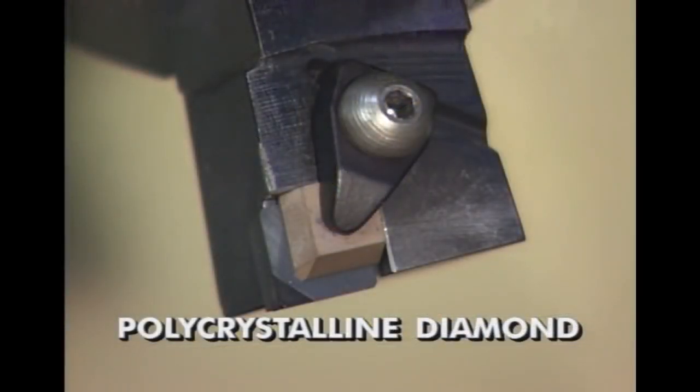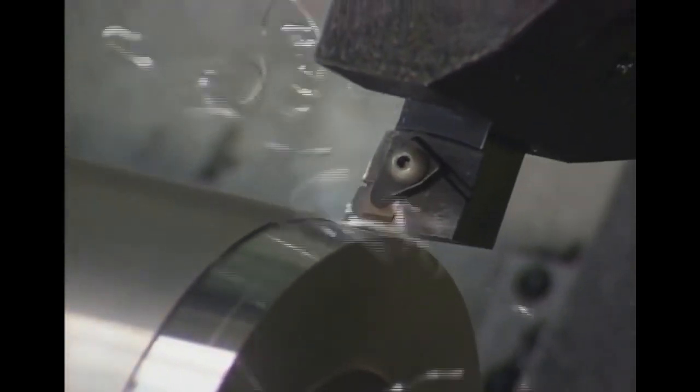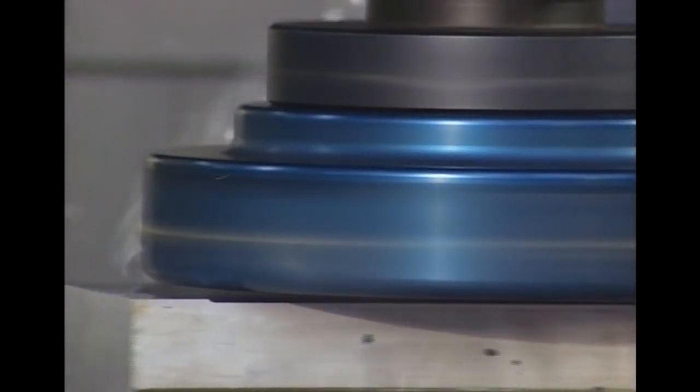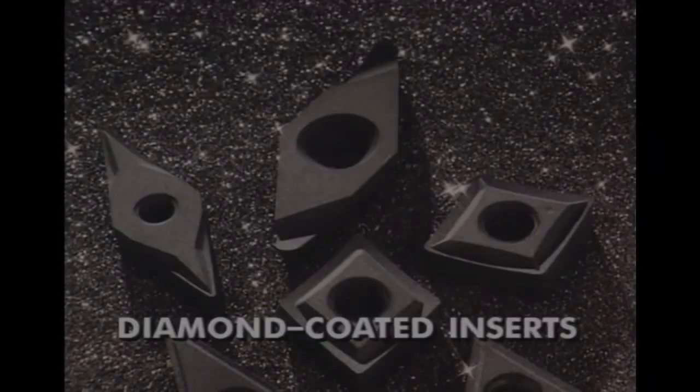Polycrystalline diamond, or PCD, is composed of micro-sized diamond particles in a metallic binder and is over 50 times harder than common carbide. PCD is used for non-ferrous applications and also cuts abrasive materials such as glass, reinforced plastics, and hardwoods for furniture manufacturing. In some high-volume applications, PCD inserts have machined parts for 6 months before having to be replaced, outlasting carbide by up to 100 times.